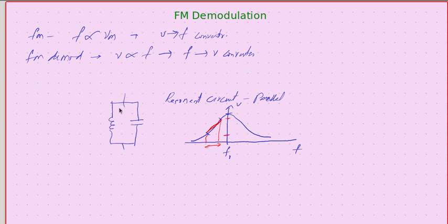So if we have some circuitry with a tank circuit, and the property of the tank circuit is having impedance in this shape, and if we can make use of this circuit as part of our amplifier, then whatever input you apply, depending on the frequency of this input, the impedance keeps changing.